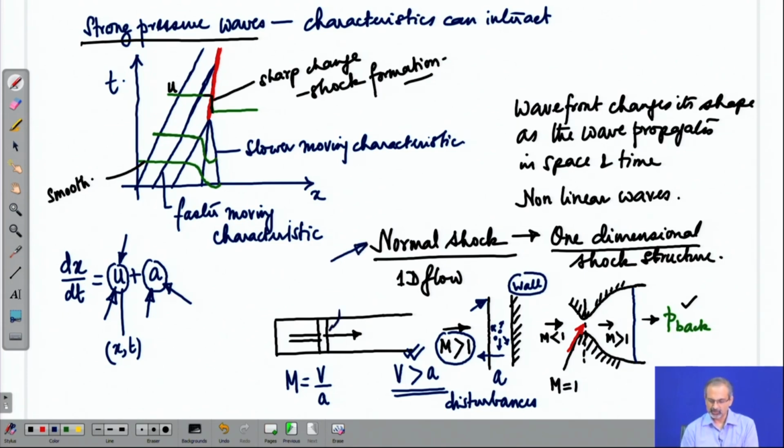In this situation too, the moving surface which is creating the compression is flat in nature, and therefore, the high pressure front which finally forms a shock wave ahead of it also has a flat nature, which is again a normal shock. So, in nature we also observe shocks which are tilted to the flow direction. Those are called oblique shocks. We will deal with them in due course.